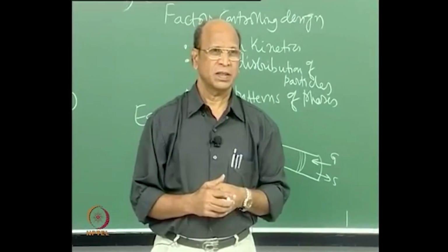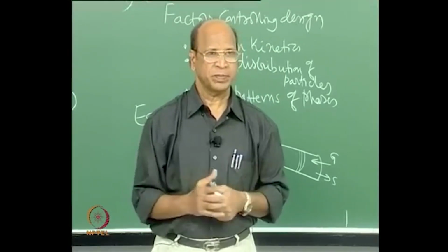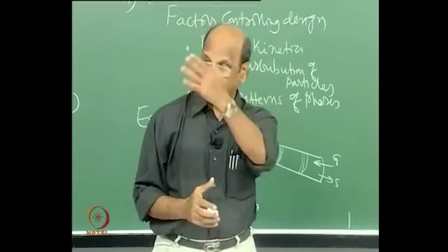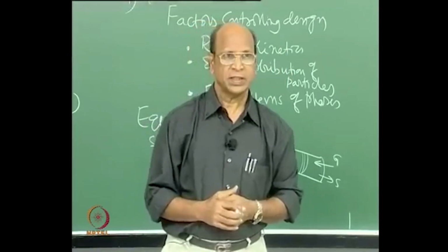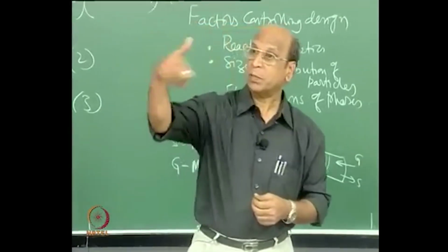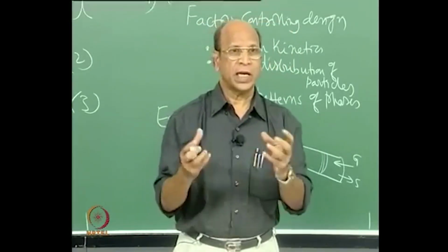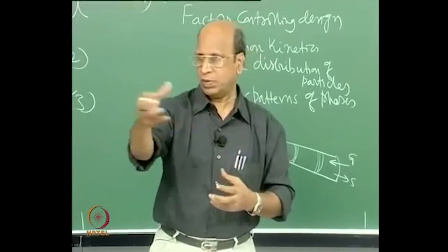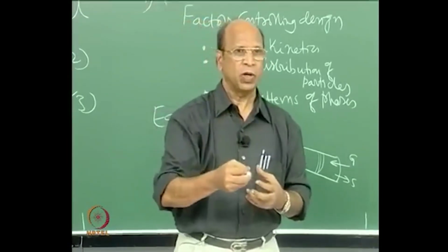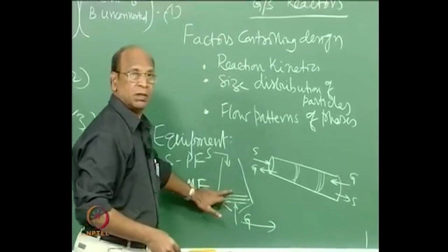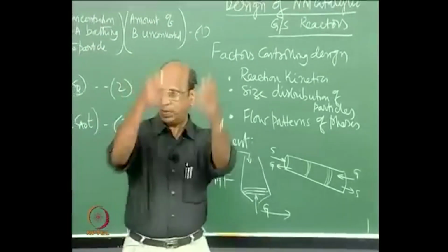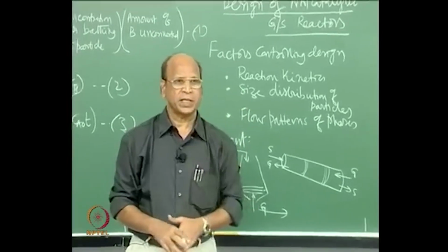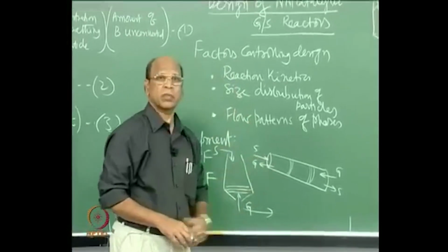And by the way, what is the size of the particles they use in a blast furnace? Guess. One kilometer to any size. Yeah, that is a very good guess. Four inches. And that is why they have the pelletization plants. They cannot simply use very fine material, because during mining they also get a lot of powdered or small-particle ore, and because it is a blast, so much gas is blasted inside. What will happen if you have fine dust or small particles? All of them will come out. They will be thrown out.